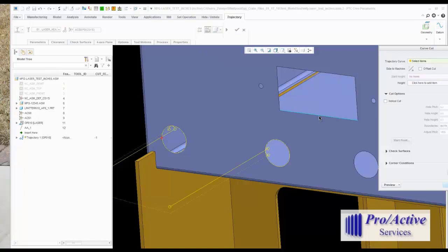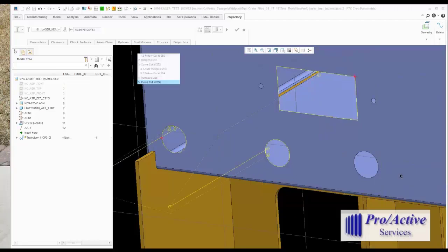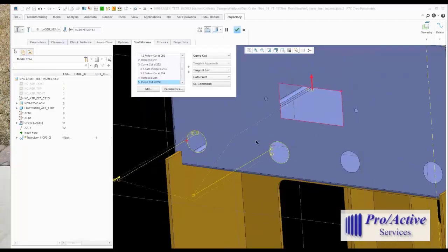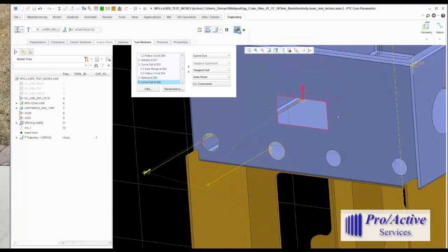Here I'm going to cut that rectangular window. Now I do want to point out the starting position can be graphically dragged to where you'd like it. You notice the number associated with where I dragged it to. This is basically a percentage along that edge. So if I want it to be exactly in half, I can type in 0.5. That will be halfway along that edge. So I could continue cutting the rest of the cutouts with this method.